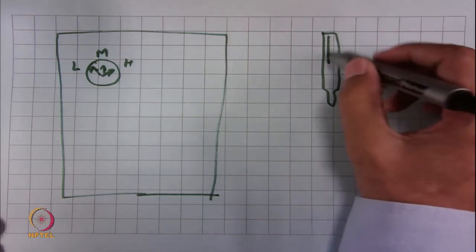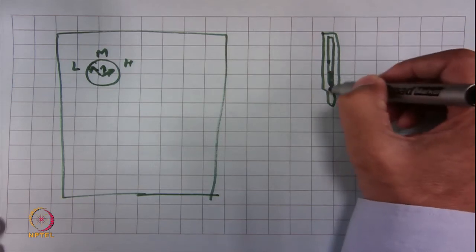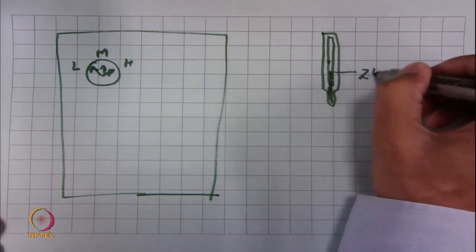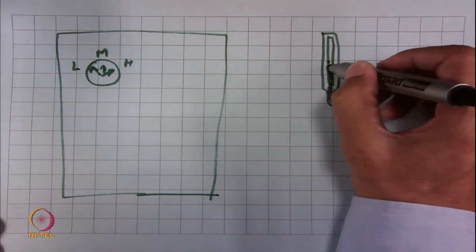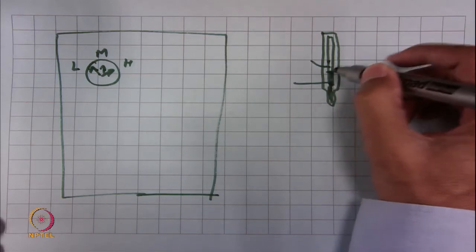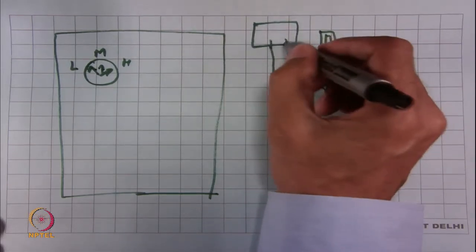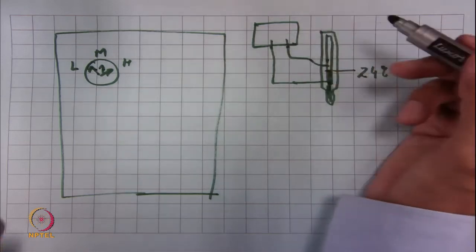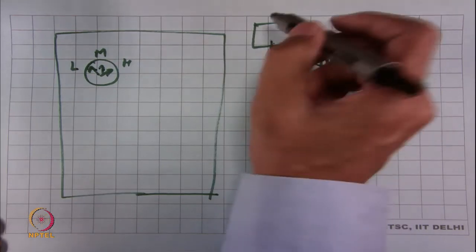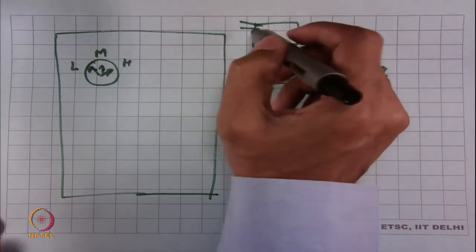Maybe I'll draw it again. Let's say this is the mercury inside, and we have it represent a certain temperature, say 24 degrees centigrade. There is a metal conductor which is immersed in the mercury at the point of setting. This goes to a triggering circuit, which has some diodes and so on, and I'm right now not remembering the whole circuit, but whenever there is contact between these two, it powers the relay, and that relay in turn energizes the compressor contactor.